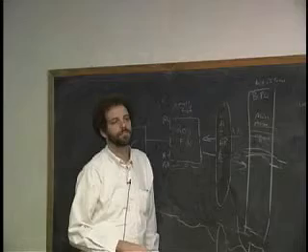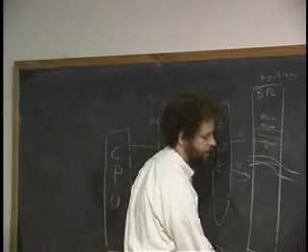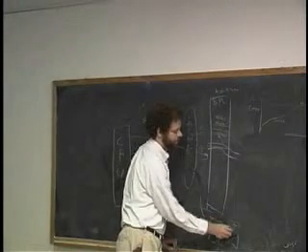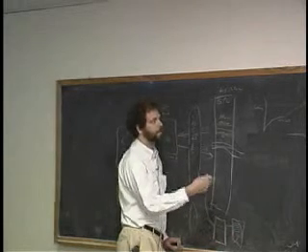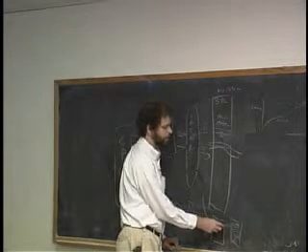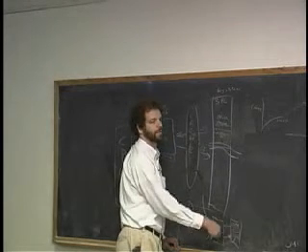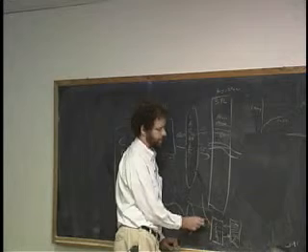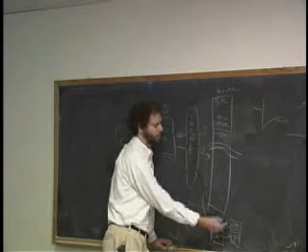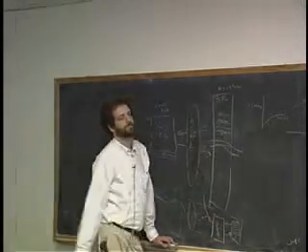Is VRAM intrinsically different from SDRAM? It is, and the reason is that on the other side of here is a screen, and the screen forgets all the time. There's a beam that scans over and over, and when it's done with one scan in 1/60th of a second or a little less than that, it goes back and has to start all over. So constantly there's a stream of read requests coming into the VRAM and data flowing back. Incredibly high rate data going on this side. And then on the other side there are reads and writes going in from the processor, typically at a much lower rate. And so VRAM is specialized to allow the right-hand port to do that all the time and the left-hand port to do it less of the time. Whereas this is sort of a single-ported system here.